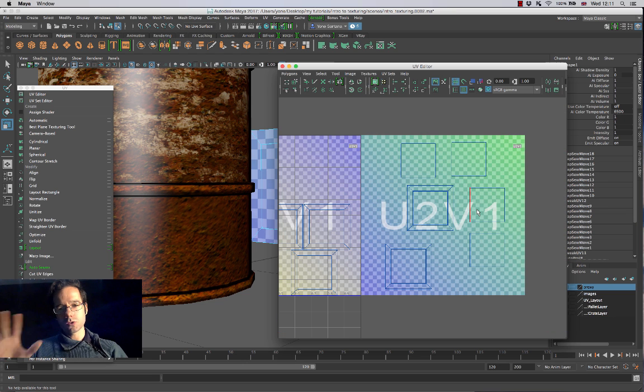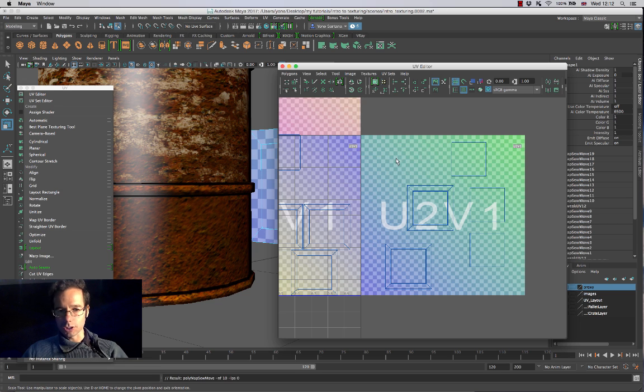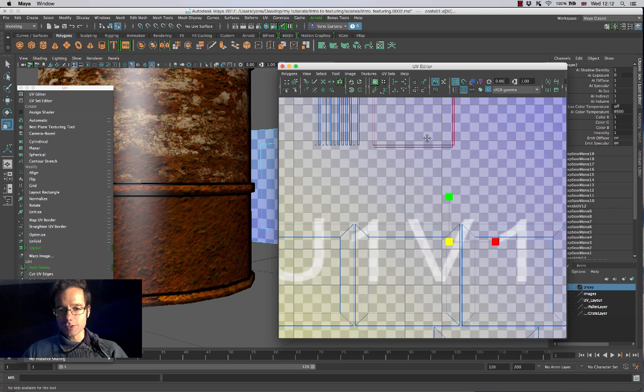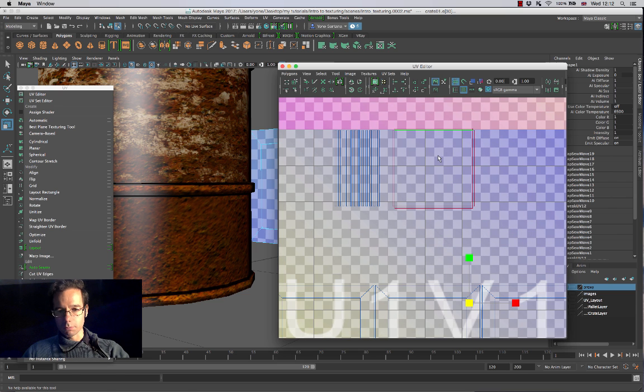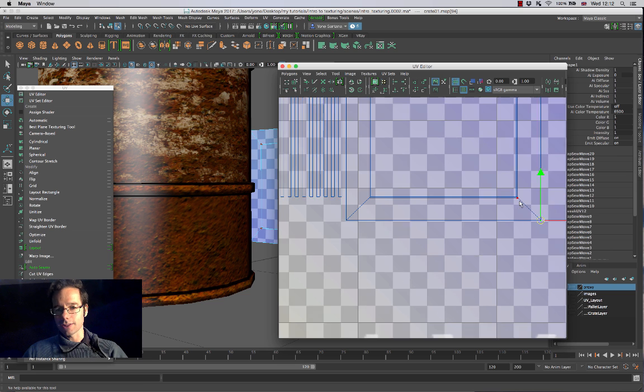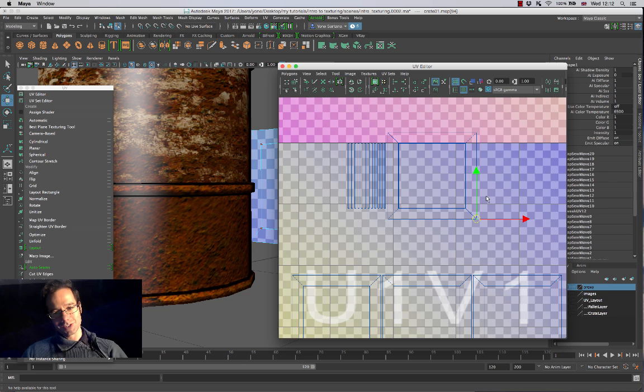If you know how to do your selections the process becomes really quick, because I can click and drag and select all of those edges and hit G, and it will do a move and sew. It just jumped over here to the other side, but that's still fine. I can grab all of these again and do a quick move and sew, and that will connect everything up in the way that I want. If you don't believe me, let's go to UV modes and do a little check to make sure that everything's connected together. That's connected together. That's connected together. But that's speed and efficiency, guys.